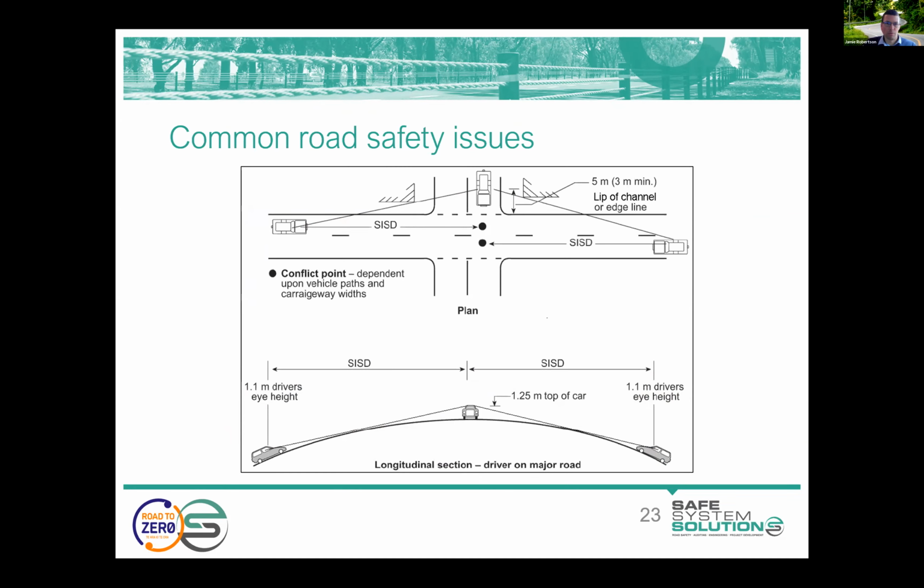There's a range of reaction times provided for in Austroads, and in constrained situations, we can sometimes adopt as little as perhaps 2 or even 1.5 seconds. I know in Victoria, we typically go with 2.5 seconds.